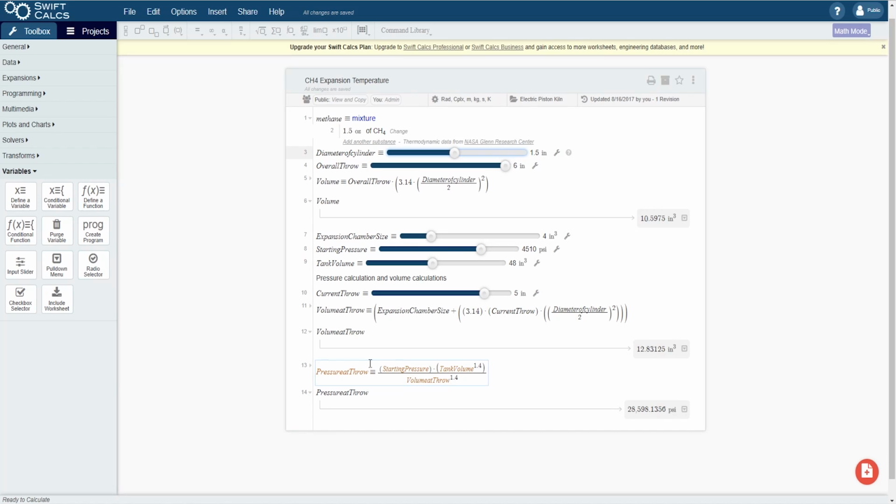Luckily, you could put a meter on it, right? So you can put a PSI reading meter on it. What we want is to drain all that pressure as it goes all the way throughout the throw. So what we need to do here is find out what our regulated pressure is.